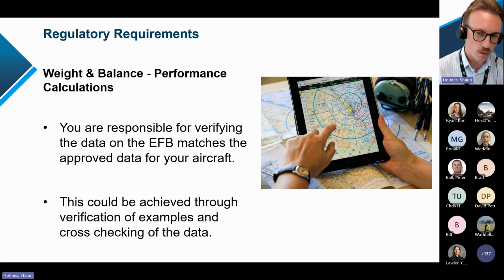Now, for air transport operators and some certificate holders, in particular 138, there are additional requirements prior to using the EFB for such things like weight and balance. Again, I would recommend having a look in the AC 91-17 to have a look at some of those requirements. Typically, we're talking about involvement of a weight control authority and some assessment and approval processes there. So a little bit of information for operators. As I mentioned, for private pilots, it's about ensuring that that information is correct and in line with that approved data.